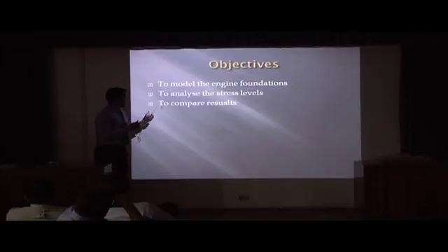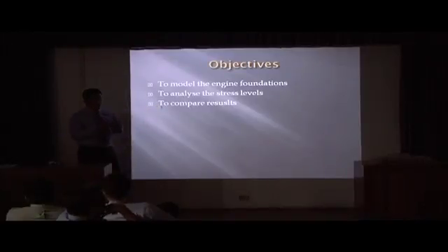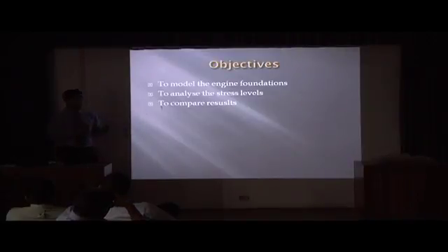First, we are going to model the engine foundations. What does this mean? To model is to see the problem in a simplified way to make the analysis a little bit easier. Then we're going to analyze the stress levels. We must remind that the yield stress of the steel is about 2,400 kilograms per square centimeters. So we must stay under these values to have an appropriate design.